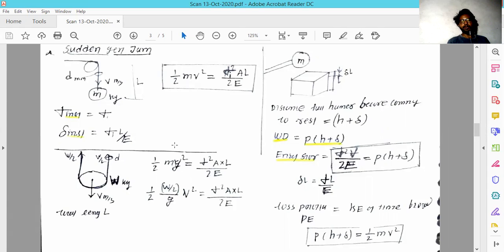So the mass and the force are going to be applied in this condition, and the mass is going to be W by 2 divided by g, which shows that half the weight is sustained by one wire and half the weight is sustained by the other wire. So we have to calculate for one wire first. This is how you can find the stress value, and with respect to the stress, you can find the instantaneous change in length of that wire.